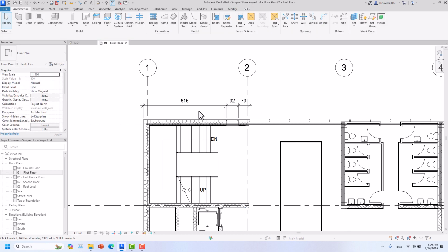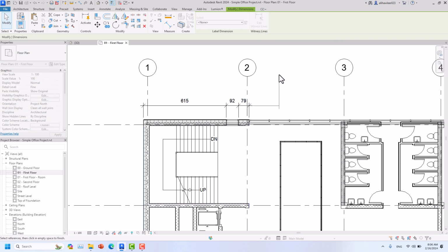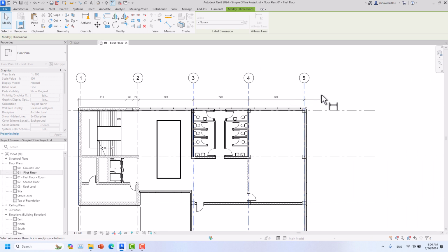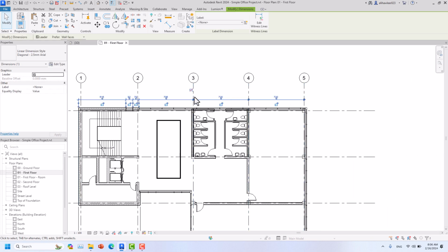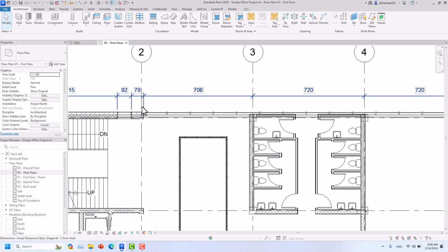Yep. Another thing is that when you click on it, you want to add something to here. You can always go to the edit witness line, EW. You can go with the EW and you can change. Click on it, and go with the empty space. For example, click this and empty space. For example, you want to delete something. For example, I want to delete this dimension, but I want to keep the rest. So click on it.